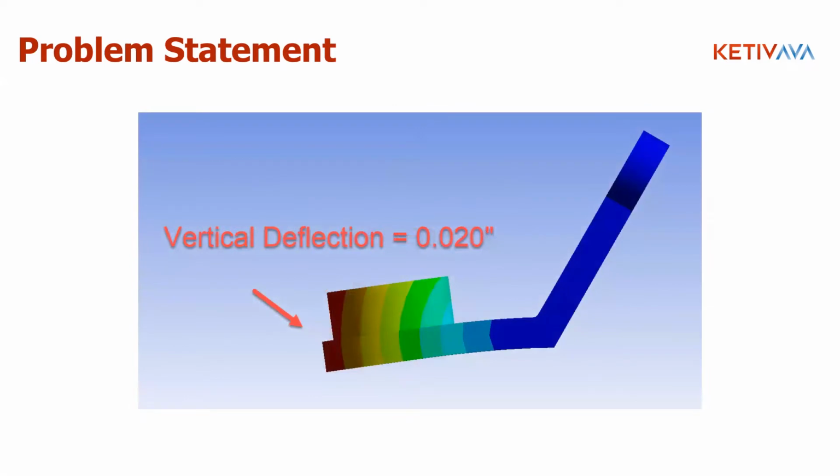And we discover that after mass producing these brackets, we didn't do a simulation. We thought it'd be fine. And we might have messed up our hand calculations initially designing this. And we discovered that it deflects a little too much. The deflection is supposed to be less than 0.02, and we are at 0.02 right now. So the story is we've already mass produced these brackets. Let's just say there's about 1,000 of them out there. What can we do to fix this bracket?